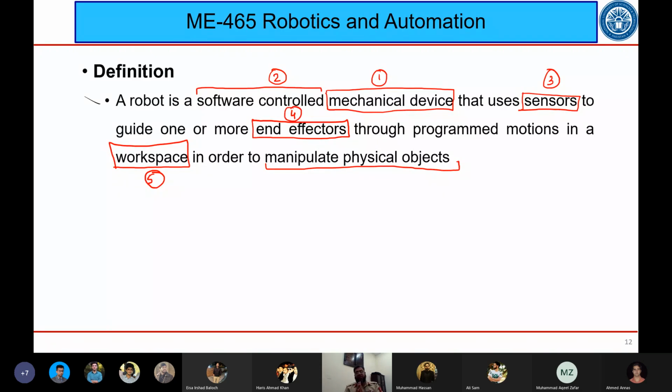And what is kinematics? These are mathematical equations, these are some matrices. So you put the angles and lengths of the links into those matrices, and those become equations, and then according to those angles you rotate your motors, and then you reach a certain place in your workspace.